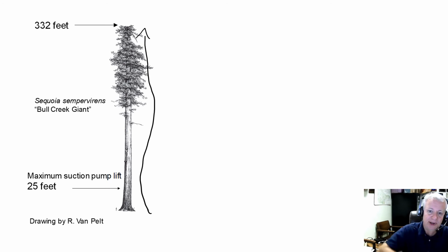Whereas when a suction pump reaches that maximum lift against gravity, and I'll show you the math in a minute, at that point it's reached the vapor pressure of water, and that water will cavitate. It will boil.